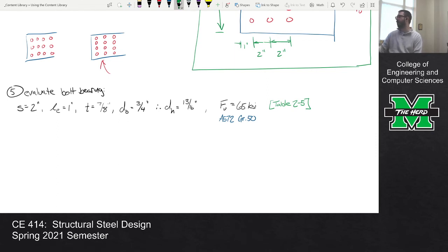If you go out and you have section loss, then you can measure the thickness and use that thickness in your evaluation. You're not going to have that on a fresh connection that you're designing for fresh construction. But when you're doing load rating, yes, you can go in and change that. You can take section loss at various points and either evaluate it section by section, or average it out or something like that. But yes.